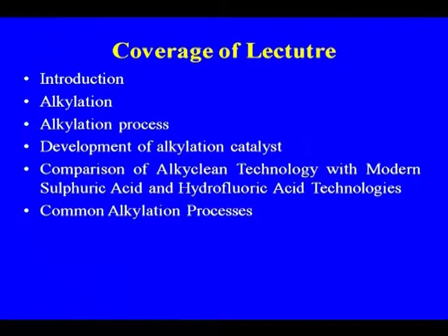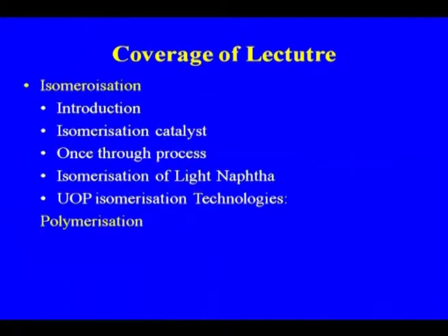The coverage of the lecture will be the introduction, the alkylation process, development of the alkylation catalyst, comparison of alkylation technology with modern sulfuric acid and hydrofluoric acid, and common alkylation processes. Then isomerization: introduction, isomerization catalyst, 1-2 process, isomerization of light naphtha, EOP isomerization technologies. And then polymerization, some of the technologies available for polymerization or oligomerization, which I told you, for improving the octane number.